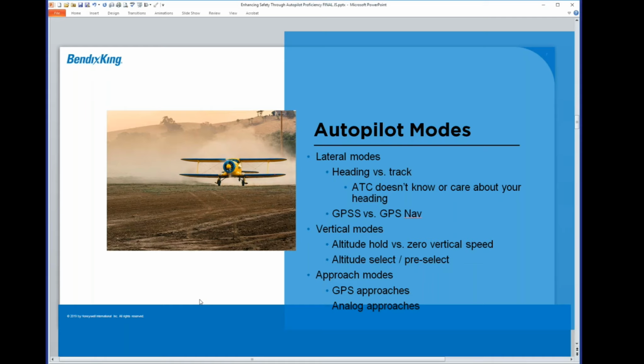Of course, there's altitude hold with other autopilots, older ones as well, but you're holding a specific altitude. If you're just looking at vertical speed change and trying to hold your vertical speed at 0, you can have drift. You can get bumped around. You can have turbulence that sets you off of that. We're just trying to keep you from climbing or descending, but not holding an absolute.